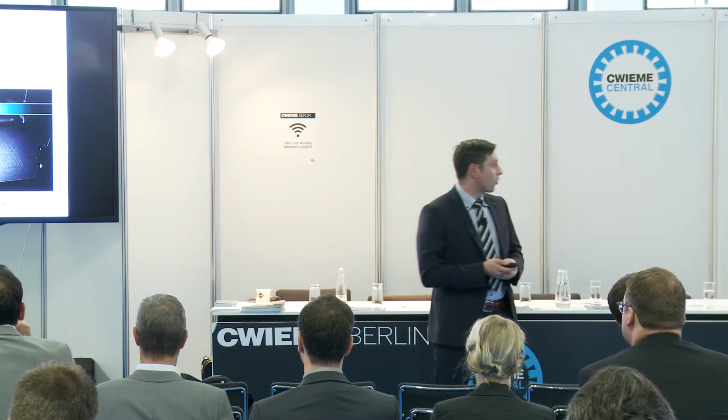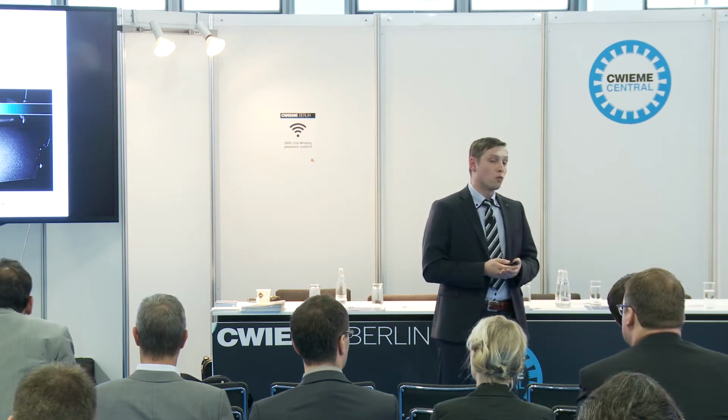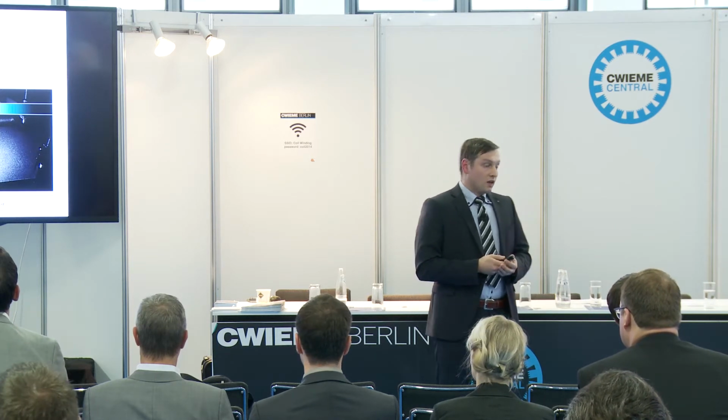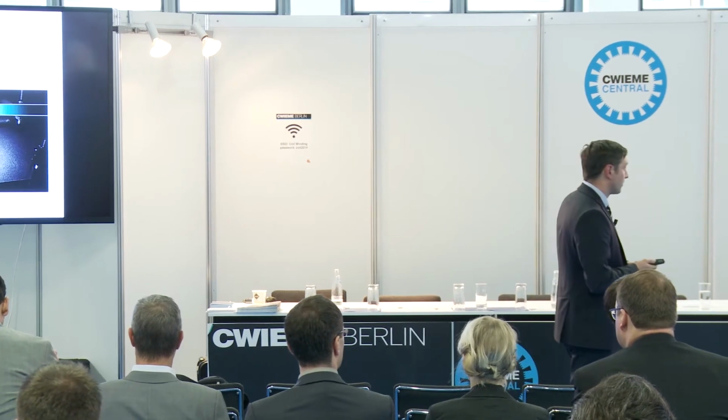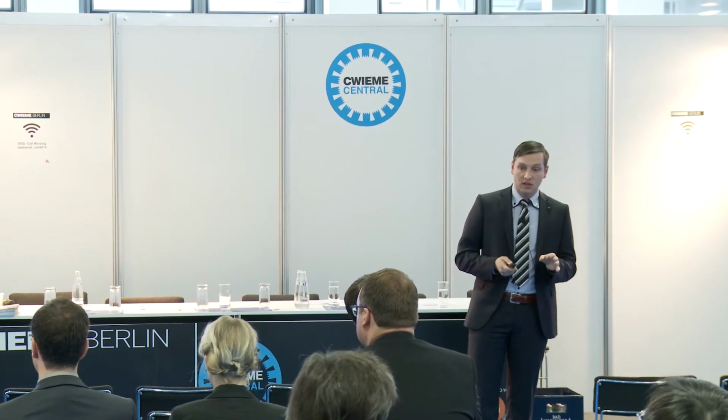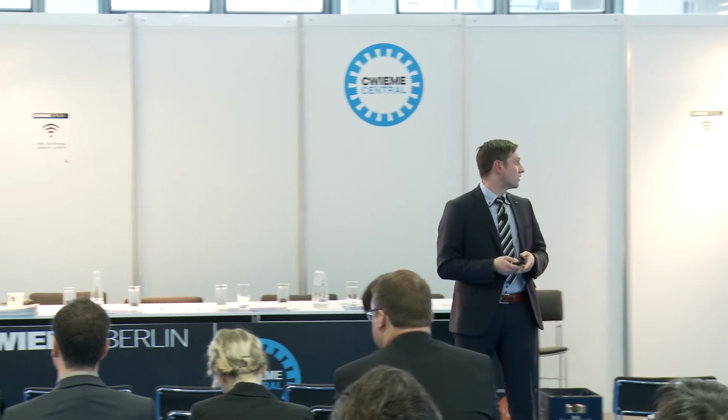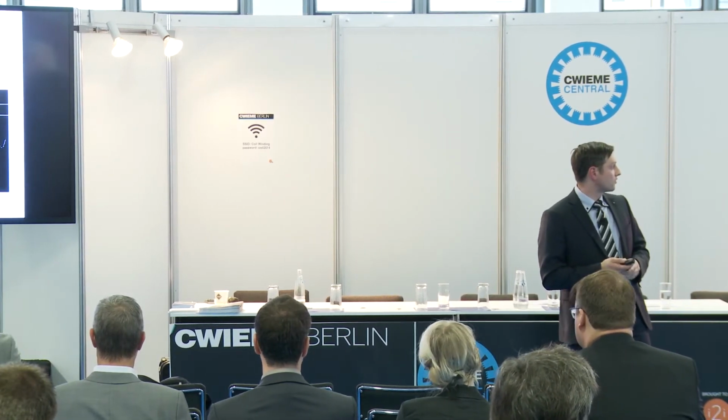In order to determine the cycle time, we did slow motion filming and calculated the cutting speed, the average cutting speed, and the cycle time. In that case, cycle time was 0.4 seconds with an average cutting speed of more than 15 meters per minute. The cutting itself just 0.3 seconds, burr removal 0.1 seconds.